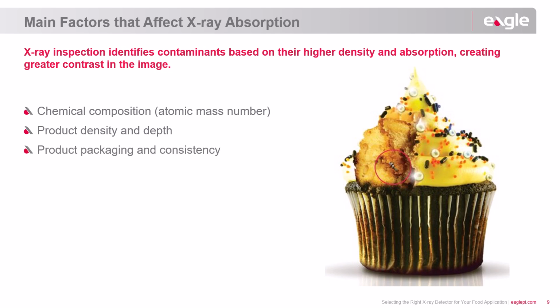3. Packaging design. Packaging, especially if it has thick, hard edges like a large meat carton about 7.75 inches thick, can create dark areas that may hide smaller contaminants nearby. For example, a tiny metal piece next to a dark edge can be hard to spot. Similarly, a small bone next to 8 inches of meat may look very similar on the X-ray.